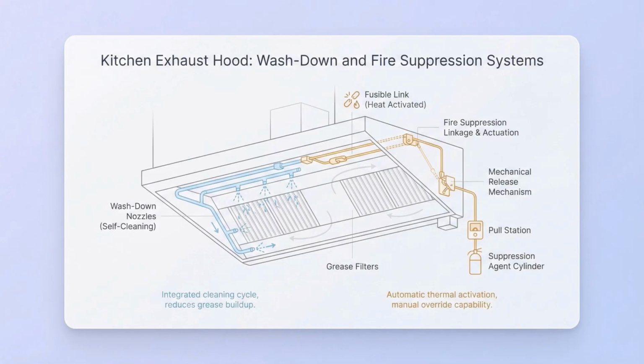Commercial exhaust hoods collect and safely exhaust air from cooking appliances. Some systems include a washdown feature to remove accumulated grease, which requires a hot water supply and a drain connected to a grease interceptor. This enhances the fire suppression system by removing the fuel source.